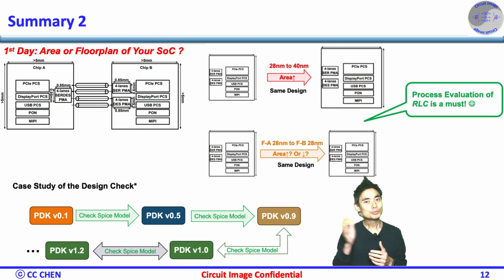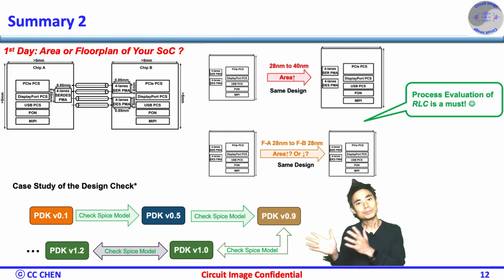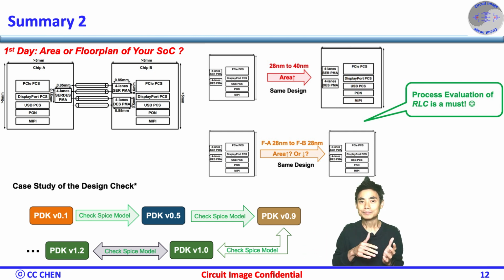Also, you might port the same process node in different foundries. Therefore, you can understand if choosing foundry B for the new process is the right decision for you between the porting effort, layout schedule, and the wafer price.